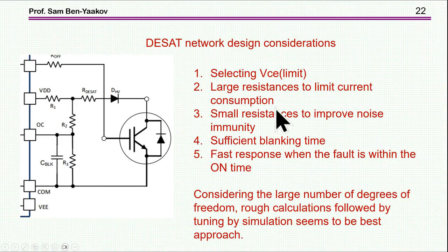On the other hand, you'd like to have small resistances, which would mean a larger capacitor, to have better noise immunity, so that the noise injected here will not develop that much because of the low impedance. And then we need sufficient blanking time, and also we need a fast response when the fault is within the on time, that is, not just at the beginning. So, as I've said, considering all this, doing simulation is probably the best way to do it.